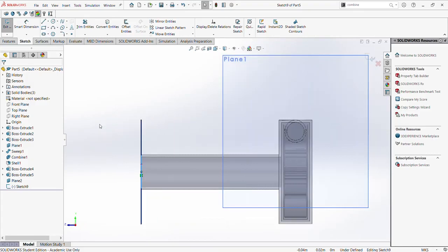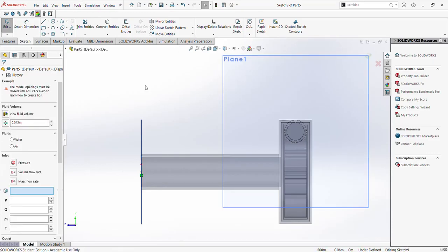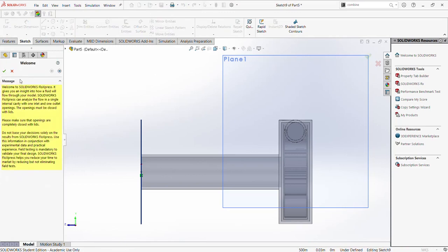Of course, if you have your own flow simulation license, you can get it through here, but the SolidWorks tools also have a different kind, which does all the work for you. So you go to Tools, Express Product, and then Flow Express, and just wait for it. If there's no warning, that means your lids are perfectly fine and there are no other openings in your design.